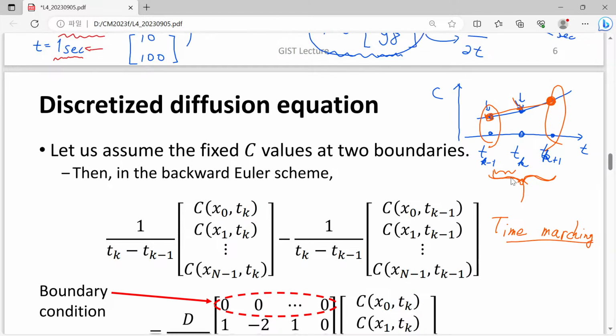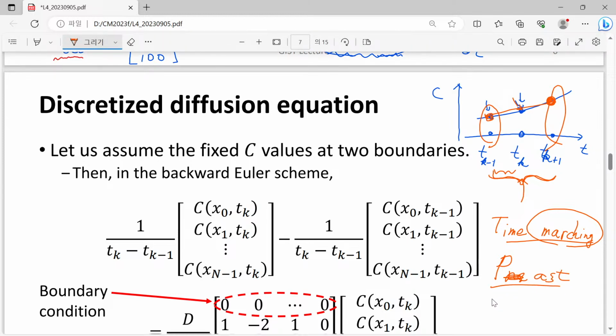Your suggested way is quite good when we have past value, present value, and future value at the same time. But unfortunately, we are doing the so-called time marching approach. So we assume that we know the past value. However, we are now trying to calculate the present value, and there is no hope of calculating the future value right now.